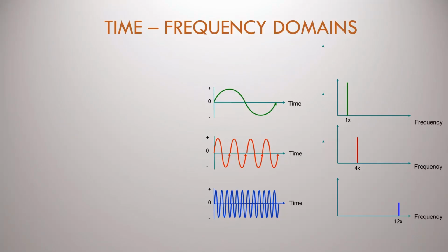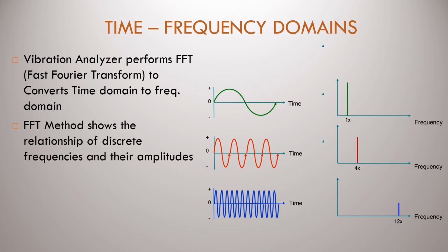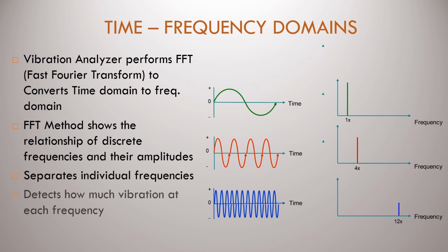Frequency domain analysis approach: the vibration analyzer performs mathematical techniques such as FFT, fast Fourier transform, to convert time domain to frequency domain. The FFT method shows the relationship of discrete frequencies and their amplitudes. This separates individual frequencies and detects how much vibration there is at each frequency.